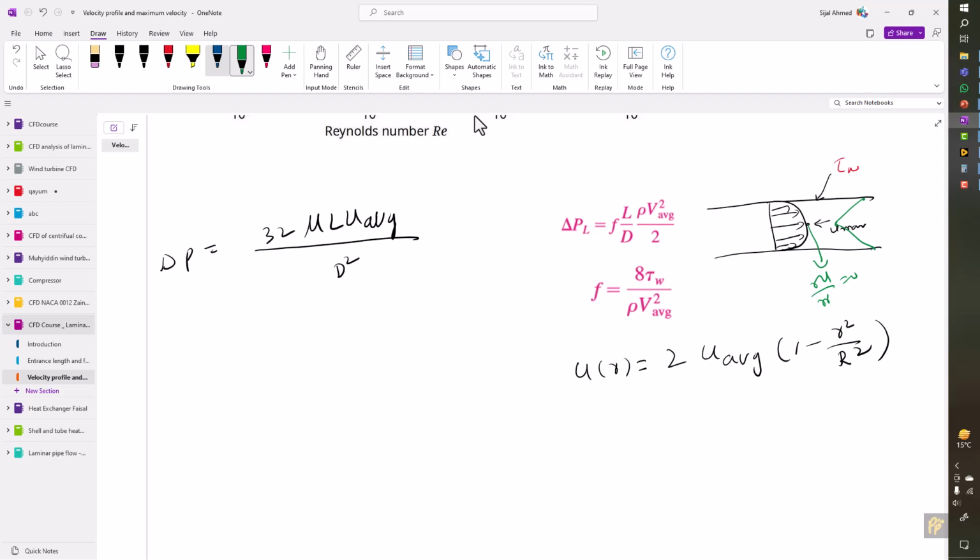and the formula for the shear stress is minus, that is to make the sign positive, because the velocity gradient will be negative, so to make it a positive quantity, we put the minus sign, and partial u by partial r. So this is about the simple shear stress.